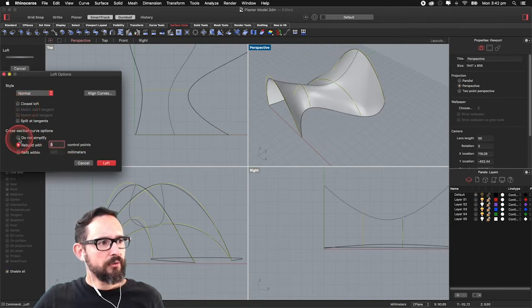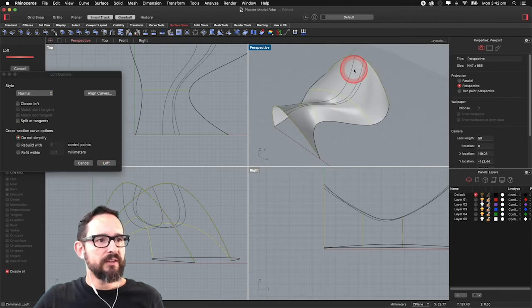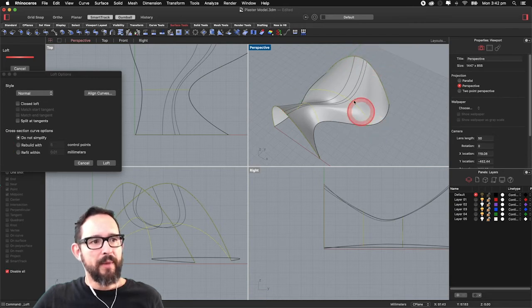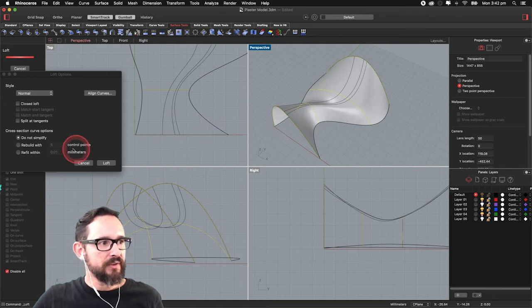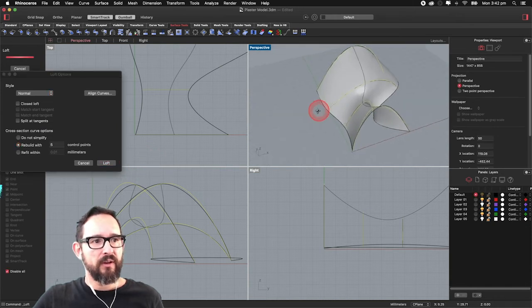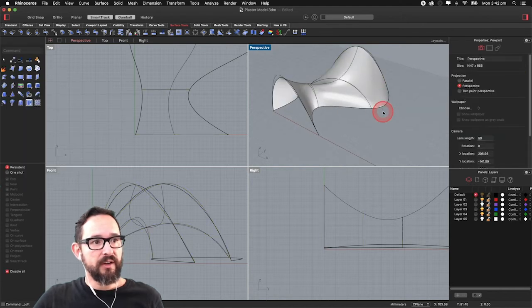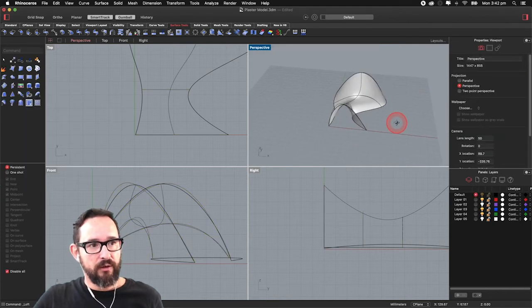And also, if you don't want to simplify, you start seeing these curves. The reason why this isn't even like it was before is because some curves might have more points than others. So these curves were done with 3 points, and this one I made with 4 points. That's why I started having this uneven kind of ISO curves on the surface. So you can actually rebuild with everything, and every curve will have 5 points of definition, and then you have a very smooth and clear surface. So this loft is fine. This is one that can create that kind of surface.